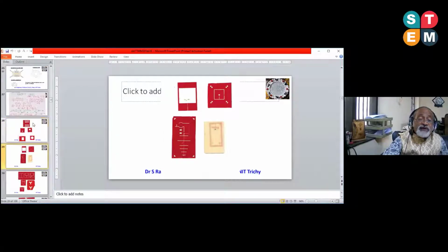So this is Yagi-Uda antenna. Yagi-Uda antenna, each director, reflector, and spacing, it is all in terms of lambda G by 4. Not only lambda G by 4, 0.3 lambda G, 0.2, it has got a geometrical progression. So everything is lambda G by 4.